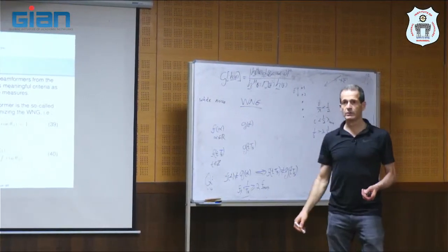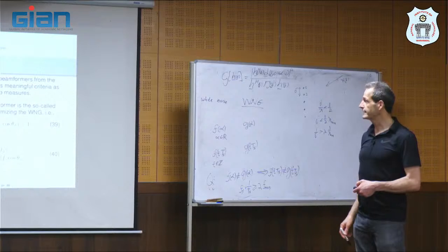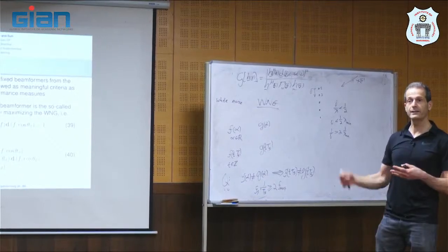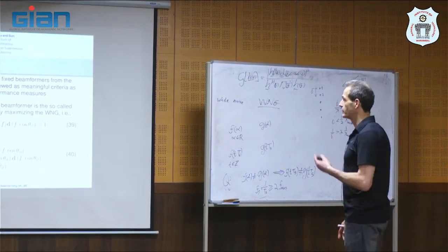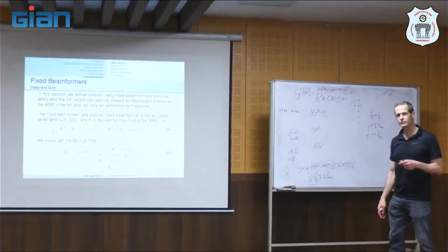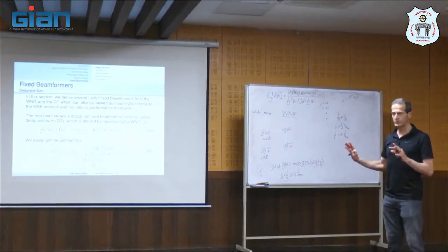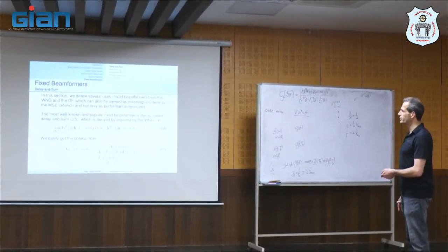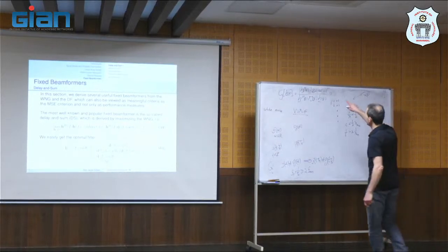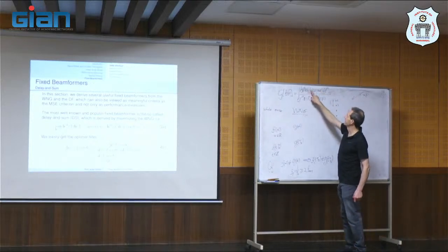But actually, we can show that the delay and sum beamformer is obtained from maximizing the white noise gain. This is a beautiful way to say it, the relation between delay and sum and the white noise gain. I can also explain the intuition behind it in a minute, but before, we want to understand the formulation. How do we achieve the maximum white noise gain? We want a distortionless response to a certain direction, so this equals 1.